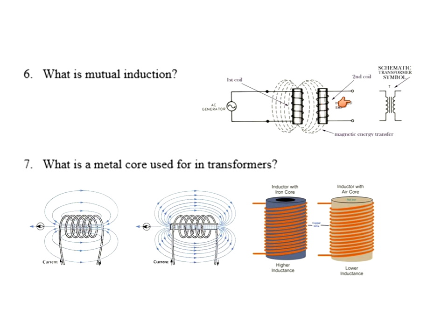And he also said that if you put current inside of an inductor, it will generate lines of flux. So putting those 2 concepts together, we can actually create a transformer. That's why sometimes transformers are called isolation. They're not electrically connected to each other, but the lines of flux are what create the electricity in the secondary. This is generating lines of flux, and this is generating voltage from lines of flux.